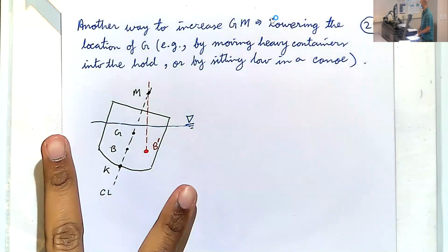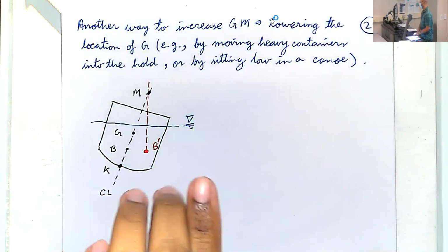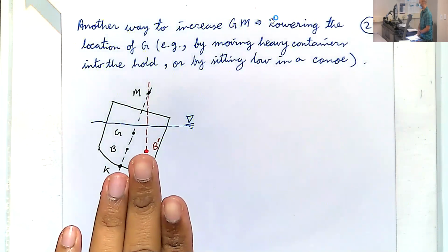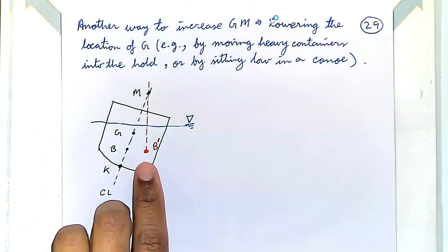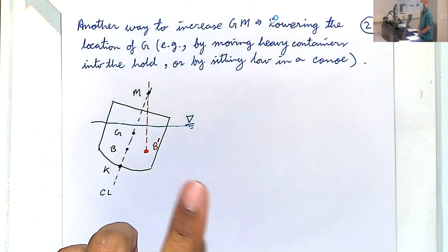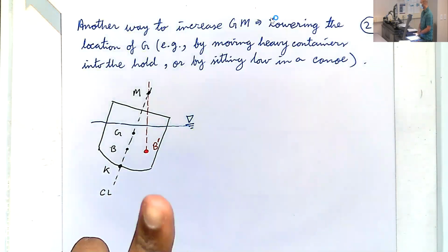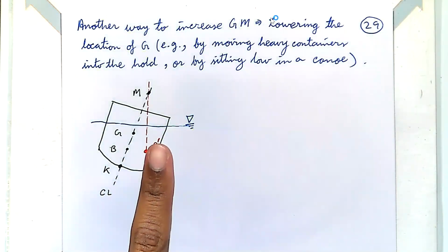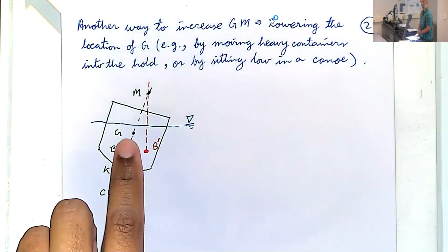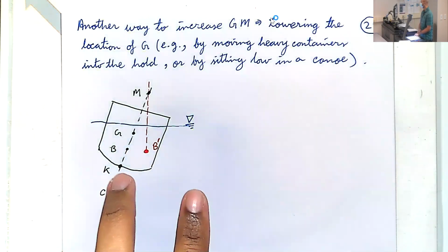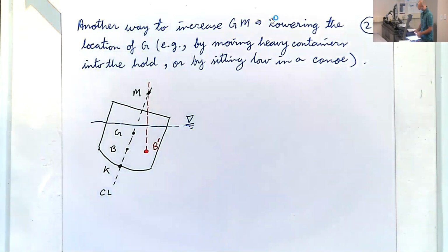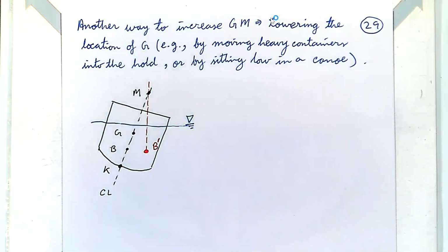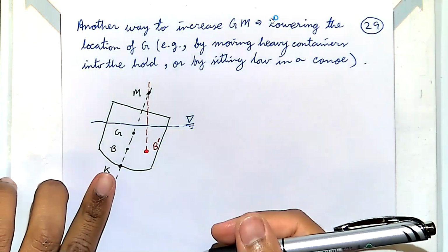What are the two forces acting on the submerged hull? Weight and gravity. Well, that's one force, correct? What's the other? Buoyant force. Yeah, so that weight or gravitational force is one and the buoyant force is the other. Where do these two forces act? What points? The buoyant force acts at B prime and the weight acts at G.